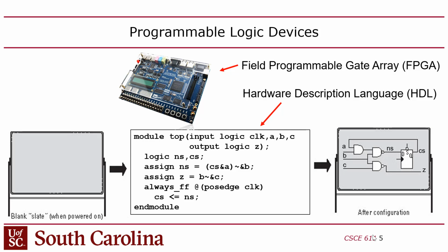Okay, so as I mentioned, an FPGA is a chip that when you apply power to it, it's a paperweight. It's completely useless until you program it. You send a bit stream in, 1 bit at a time, which takes a while, like a minute, because there's millions of bits you've got to send in. But you send the bits in, and it configures the chip. You're giving birth to a circuit when you do that. You've got a circuit that you design, and that circuit snaps into existence once you program the FPGA.